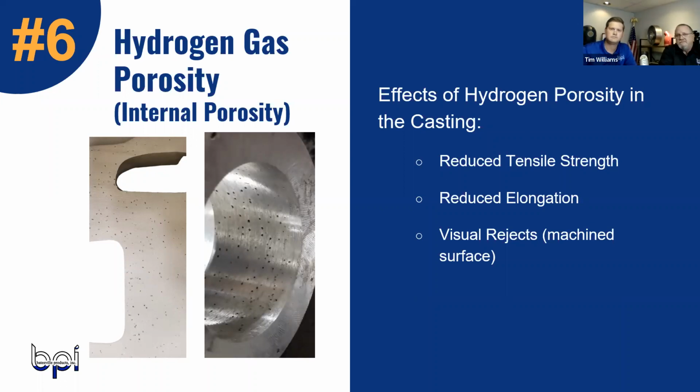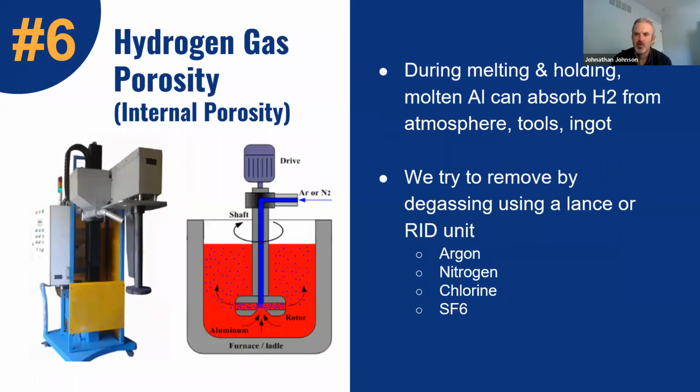Okay. Got a couple more questions, Tim, before we move on. First, what are your thoughts about adding gas to the metal to combat shrinkage? What kind of gas? Say that again, adding gas to the metal? Yeah, what's your thought about adding gas to the metal to combat shrinkage, like we do when we throw a 2x4 in the aluminum? We're adding gas. Yes, I call that organic modification.